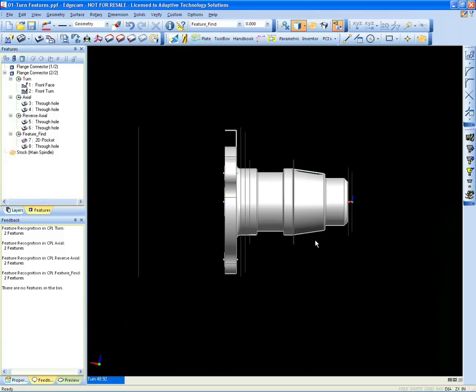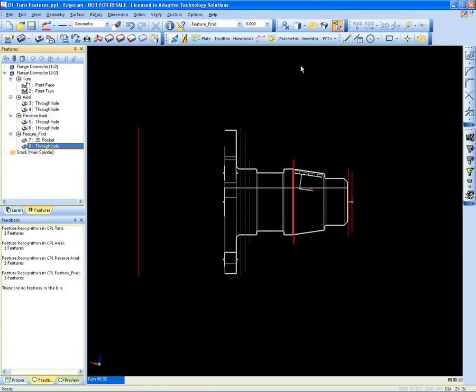In your B-axis type machines, you can now index to that face, that orientation. It will give you the proper B angle. You could then mill, drill, whatever the case may be.